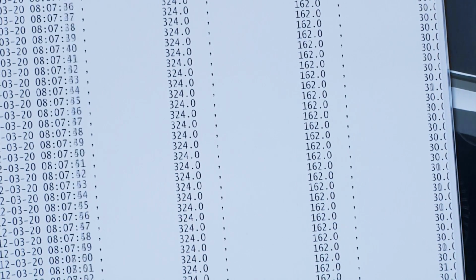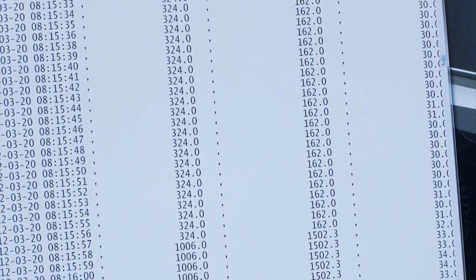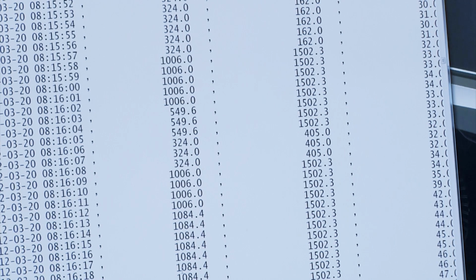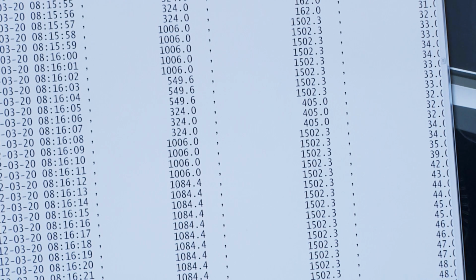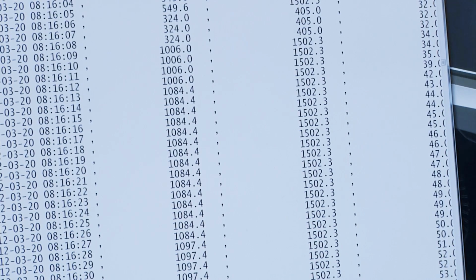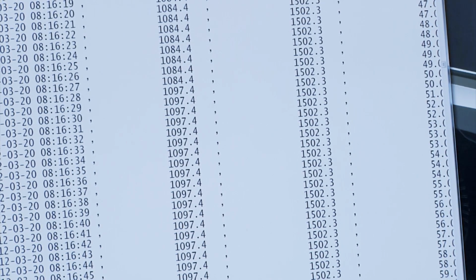Here we let it sit idle for a period of time, and then all of a sudden we can see that it ramps up. We're getting ready to have the game initialize. An initial 3D load has now been placed, and we can see we've reached that so-called base clock. But once we pass the base clock and enter an actual game engine, we can see the card ramped up past its rated specification, working at a little bit short of 1.1 gigahertz, 1084 MHz. It even got just shy of 1.1 gigahertz, at 1097. This shows you the dynamic GPU Boost occurring in real time.